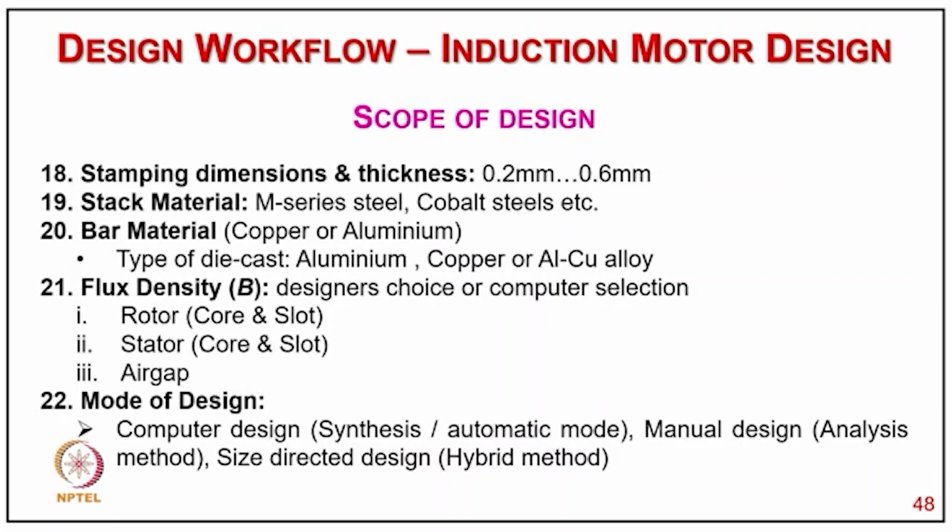Now coming to the second point, the mode of design. It can be computer design, like a synthesis or automated process, or manual design, like the analysis method, or it may be size-directed design, a hybrid of the two. The analysis means we are using the computer only for calculation but taking decisions manually, and the synthesis approach means we are doing the calculation as well as giving the decision to the computer to take the final decision. And of course another is the hybrid method, in which we use a combination of both.